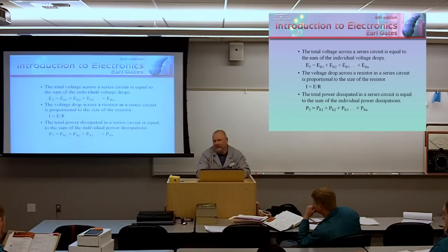The bottom line. You want the bottom line or you want the BS? Bottom line. In a series circuit, the most important thing to remember about a series circuit is current is constant in a series circuit. Period. The second most important thing to remember about a series circuit is also synonymous with voltage divider. When I say series circuit, I want you to think current's constant, and I want you to think voltage divider. That's just how I want you to look at them. And if you're not looking at them that way, you ain't looking at them right.